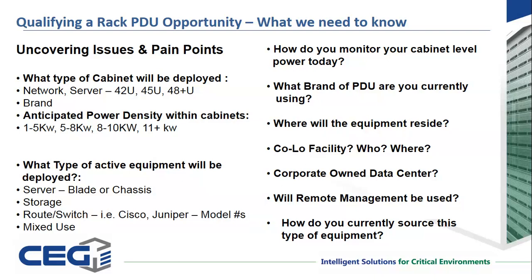You know, the types of gear they're going to be housing, is it single 1U pizza box servers? Understanding if there are blade servers or high-density chassis with high-density storage going into cabinets, because now the power supply requirements, especially for redundancy, some of these blade chassis have 3 power supplies, and they're very high wattage power supplies that you need to take into account, whereas the rest of the gear in the cabinet may be more normal, lower amperage stuff, but we've got to take it all into consideration.